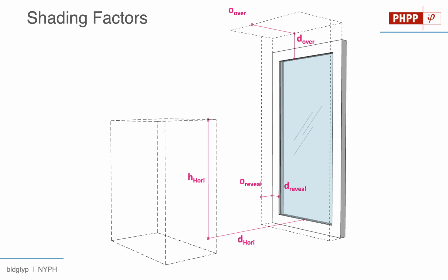At the same time, we're asked to describe, well, where is the window in position relative to the wall? With our passive house buildings, we often build buildings that have very thick, very highly insulated walls, and those can often cause some amount of self-shading on the glazing, depending on where you mount the glazing. And so we're asked to input that information as well. And then lastly, any sort of overhang information is also described for the windows.